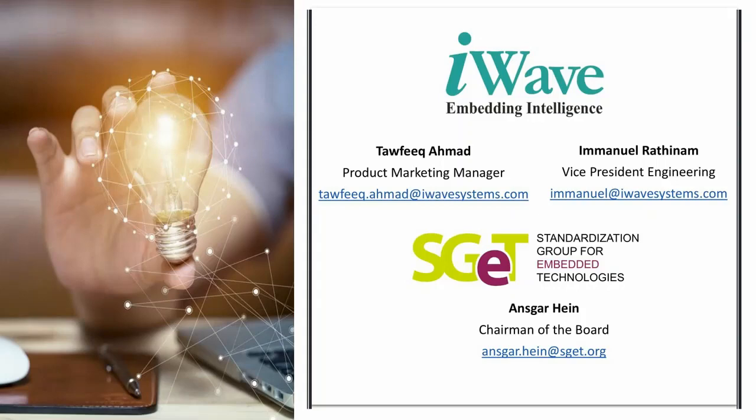And another question from Anton. How complex is designing the carrier board for an OSM when compared to SMARC or Q7? Actually, it is much easier compared to SMARC and Q7, because it is like you are routing an IC, or a kind of CPU, which has 330 plus pins or 660 plus pins. So you can easily break out. The main area where you will have complexities is in terms of production, but in terms of designing the carrier board, it's much easier compared to SMARC and Q7.